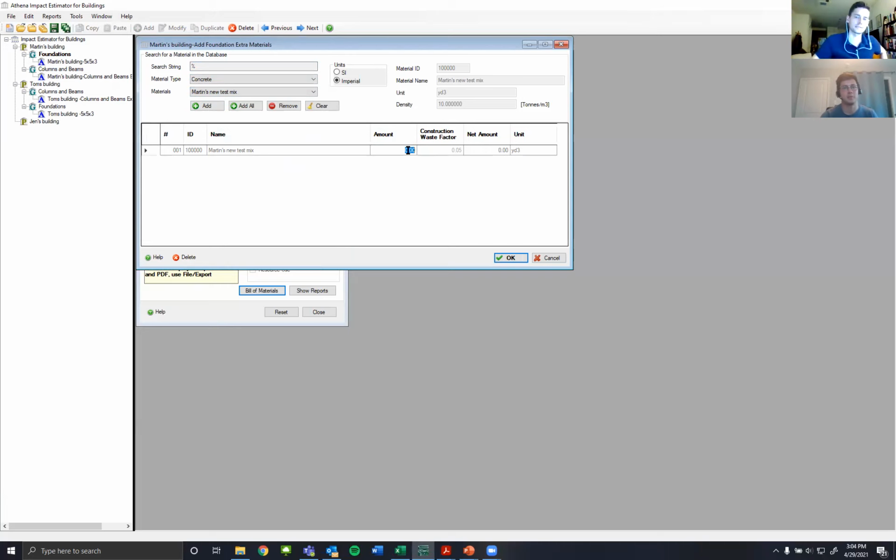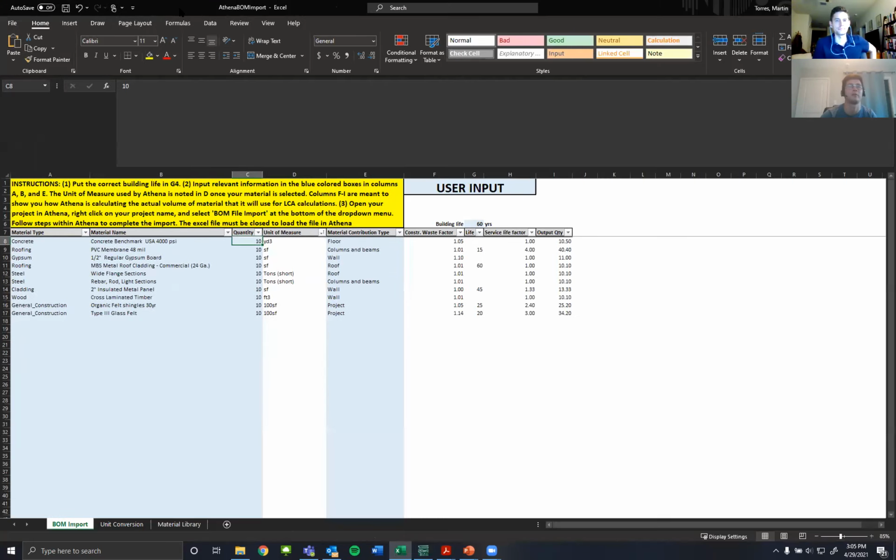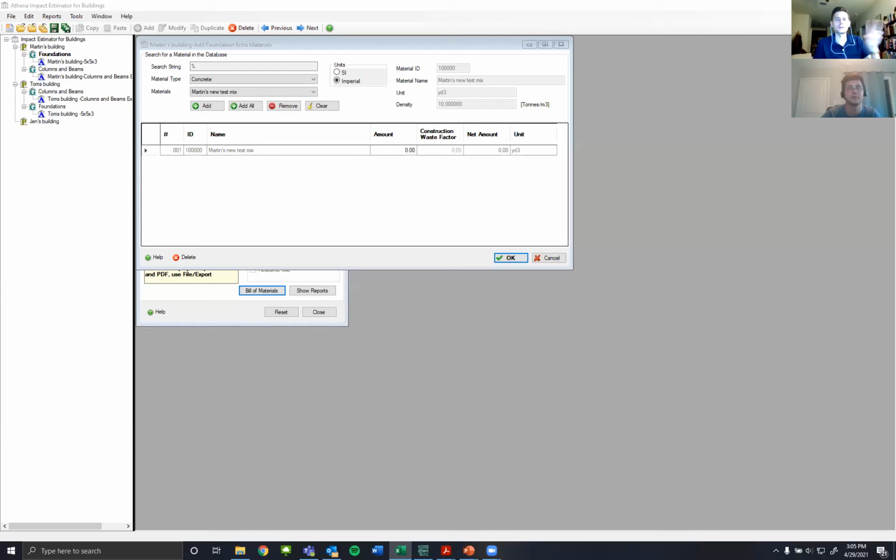So if I'm starting from a Revit model, basically I do the material takeoff within Revit, and then I assign all those materials and say, oh, this is this strength. Sum them, get my values. And then I put them into this spreadsheet and import them into Tally or into Athena. Yeah, that's probably a good method, actually. If you could schedule that out, you could go from one to the other if you wanted to run it that way. So starting and getting all of that material from Revit and putting it in here, that makes sense. Yeah.